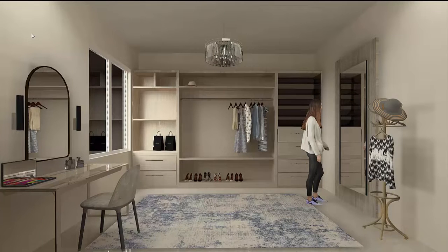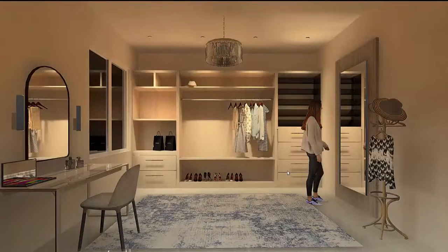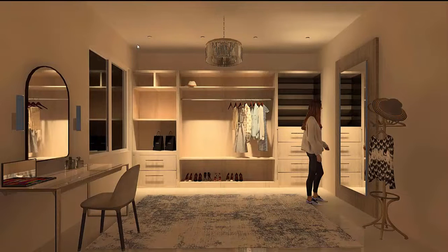Now, the other way is, in case you're not using any built-in shelf lighting or a joinery lighting for your closet, then there is another way too in which you can achieve the task lighting layer, that is by the use of adjustable downlights. Okay, now here I have placed some 4 adjustable downlights with a medium optics, and I am directing it towards the closet.